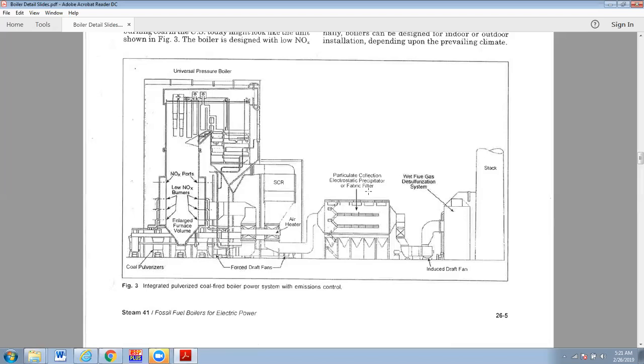They use limestone. They crush it up pretty good, put it in the water. The calcium dissolves, and then the calcium will grab onto the sulfur compounds, make CaSO4, which is a solid, and then we can settle that out, get that out of the water stream.